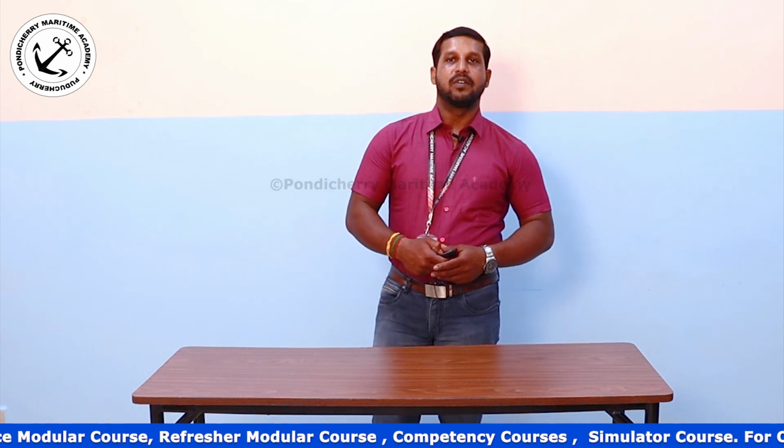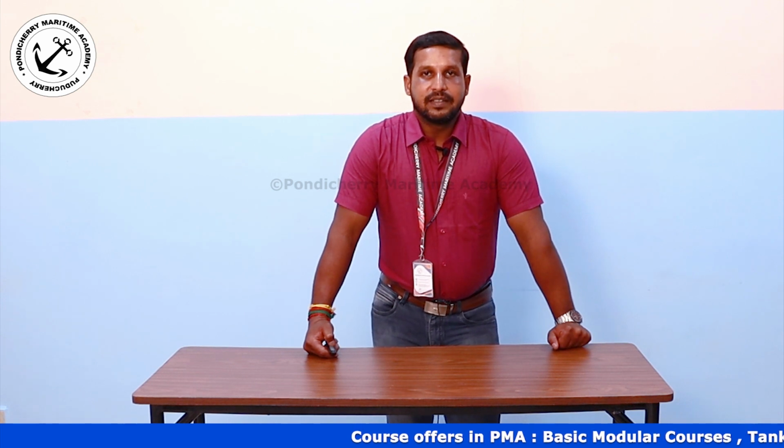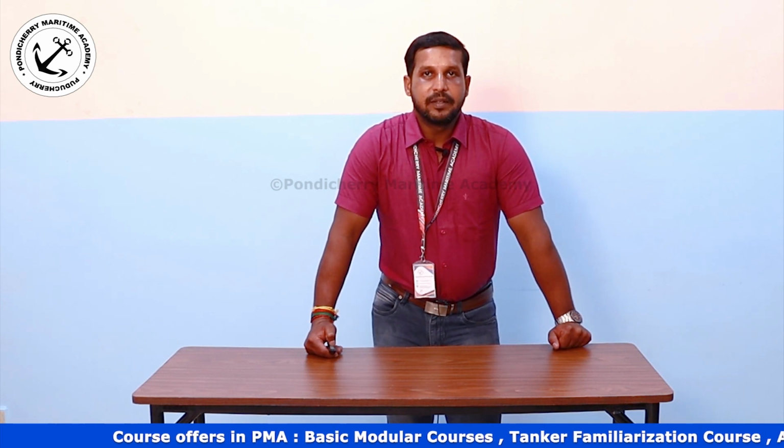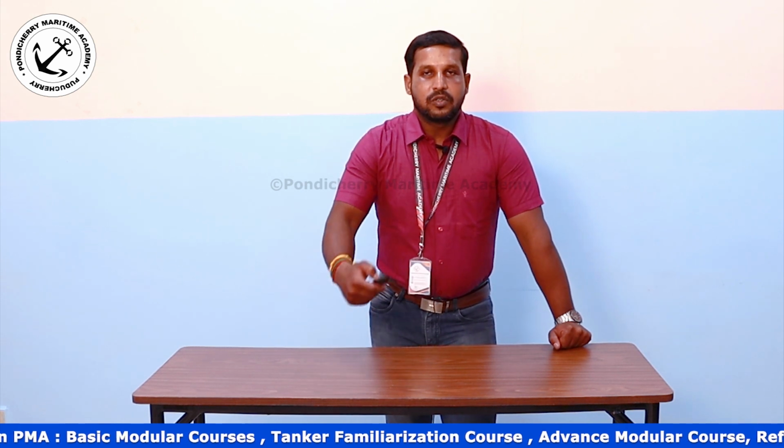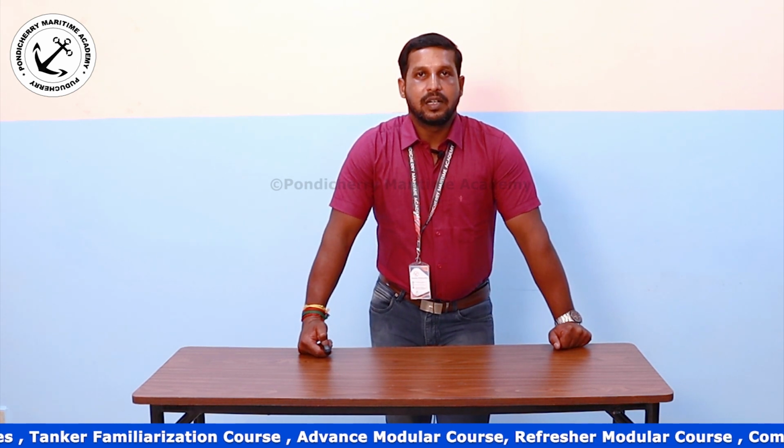Hence, the requirement for controlling the tank atmosphere is largely dependent on the type of cargo to be carried on board, and the variety of cargo to be carried at the same time, for example on a chemical tanker, right? The systems and machinery are fitted to maintain the required atmospheric conditions and the condition of the coating of the cargo tank, if applicable. The type of protection we take in the tank is by means of inerting and padding layers, for example nitrogen padding, all of which are to be considered for protection of the cargo tank atmosphere.